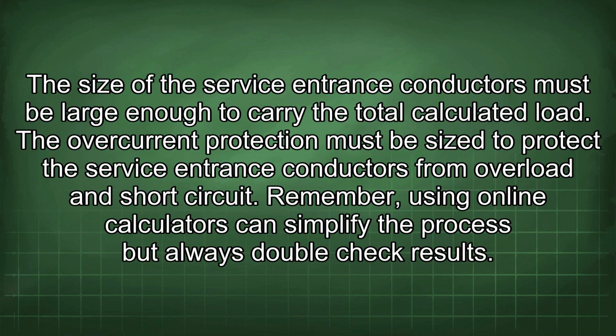The size of the service entrance conductors must be large enough to carry the total calculated load. The overcurrent protection must be sized to protect the service entrance conductors from overload and short circuit.